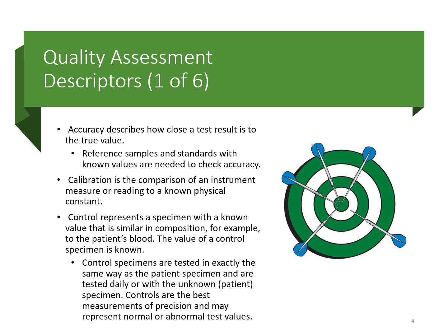How often do you hit that value when running it multiple times, back to back to back? Are you getting close to that center point value every time? If your accuracy is off, it could mean that it's time to calibrate. Your calibration is going to give you a set standard for that particular analyte.